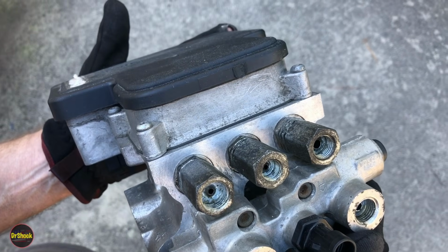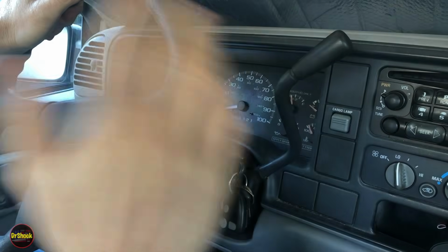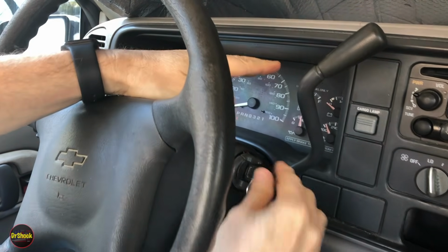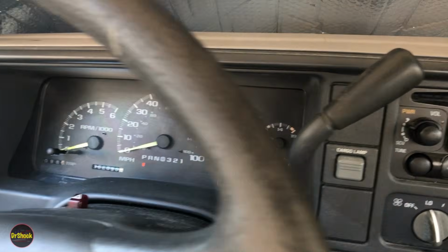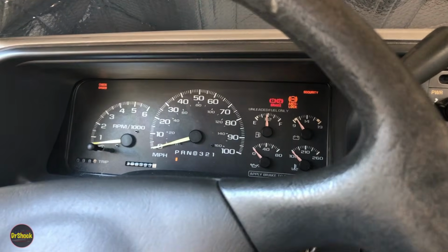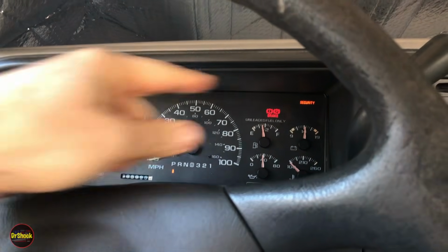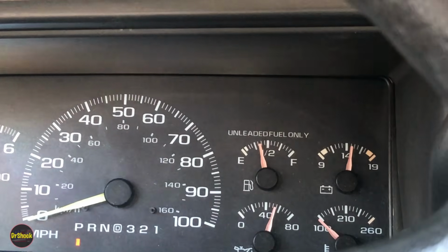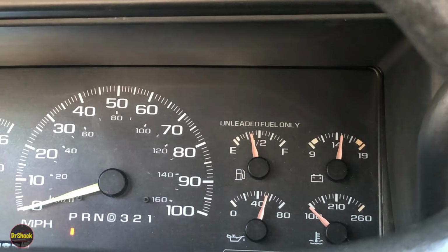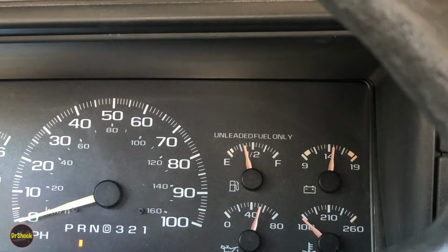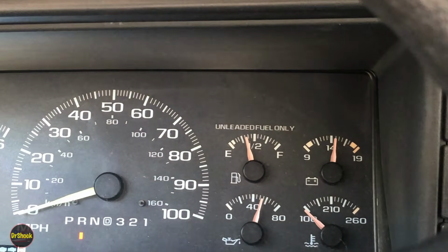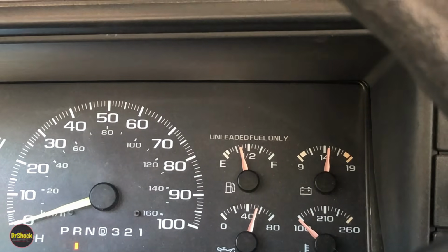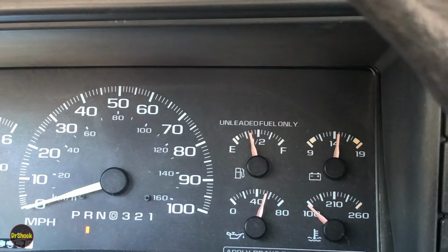So stay tuned. All right, let me show you what the code looks like and how it manifests itself. So right now the vehicle's off. You can come over here on the dash. You can see I'm going to start her up. After we get past the lamp test, we see that anti-lock brake light went out. Now all it's going to take to set this code, I'm going to put her in reverse, we just have to go a few feet and get over 5 miles an hour so that that test will run and it will fail, and then I'll show you what the diagnostic code is for that test.